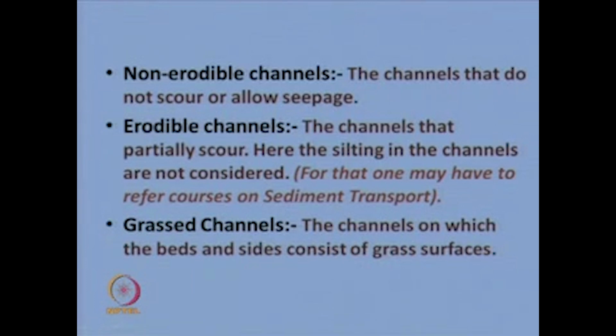So, what is meant by non-erodible channels? The channels that do not allow scour or seepage through their bed and through the sides are called non-erodible channels. Generally, you line the channel bed as well as the sides with certain materials, so as to avoid these properties.